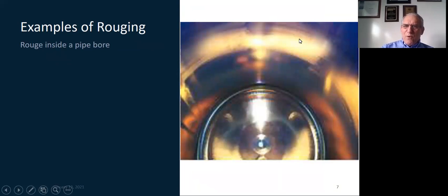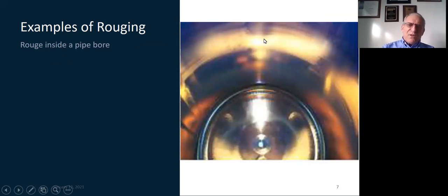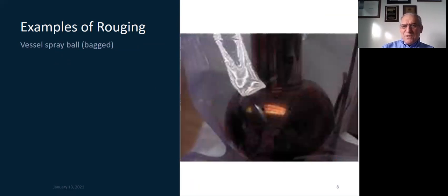Here's an inside of a bore where you get to see those very different colors of rouge, from goldens to different browns to reds to deep brick reds throughout the systems. These form due to the temperature and the exposure from the water. This rouge over here is the corrosion, showing the actual corrosion. Corrosion means that there's metal loss. And sometimes there's metal loss, sometimes there's an annealing effect. This is that blue-black rouge that we talked about earlier, or purple.